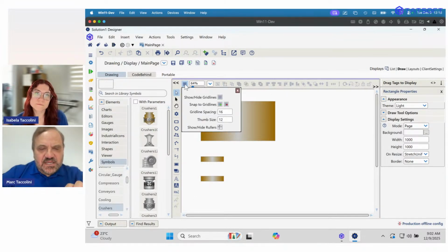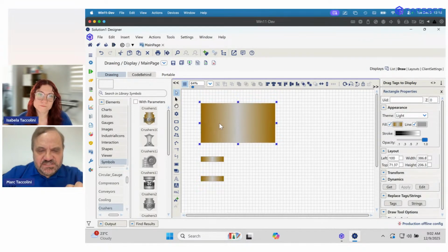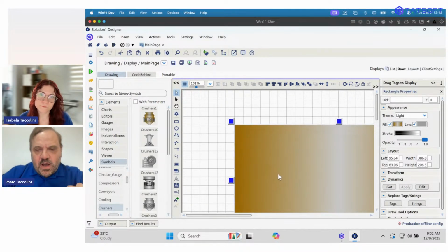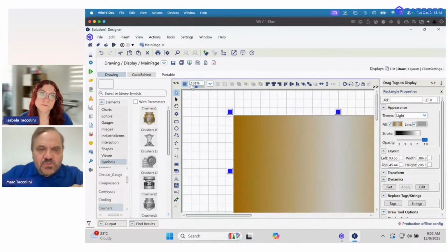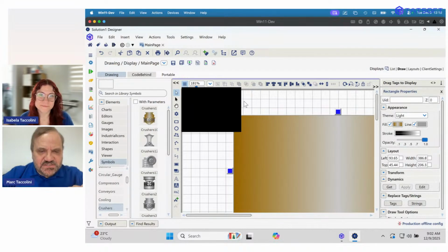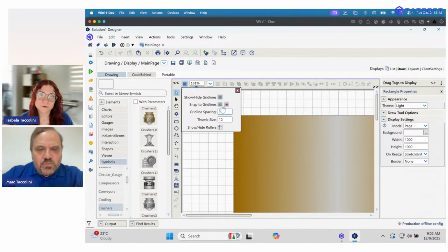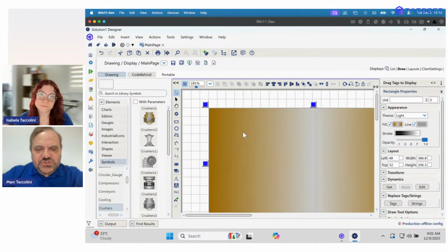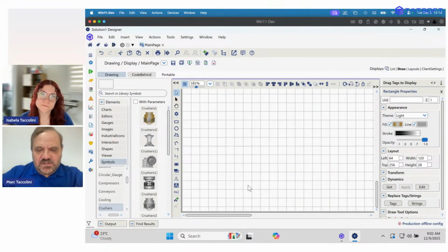The grid lines allow you to have the visual position of the objects. So when you are doing your positioning, you can define that objects should be aligned to the grids. You can do that manually or using one concept that's called snap to grids. So when you enable snap to grids and move the objects, they will automatically, as you see, move in jumps. So the objects will automatically be aligned through those grid lines. That's another way, very common.